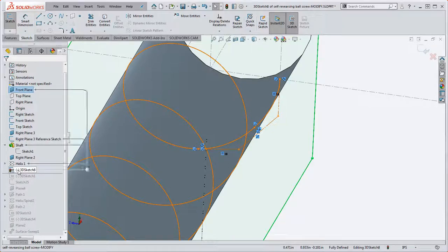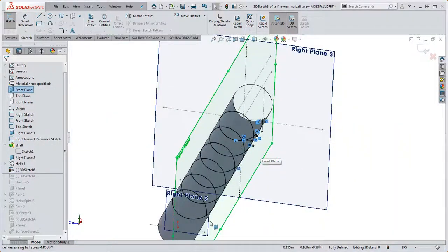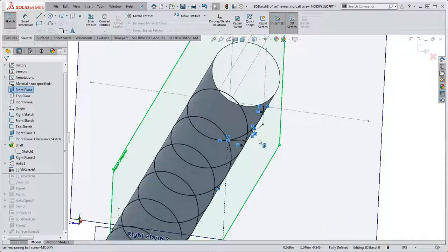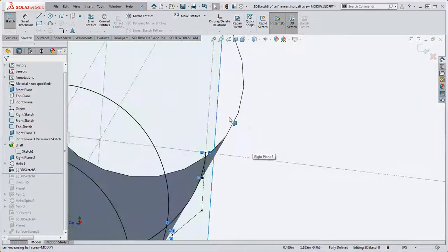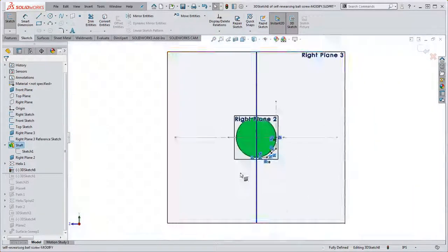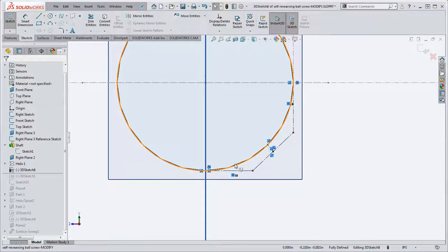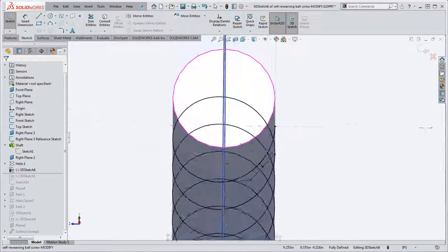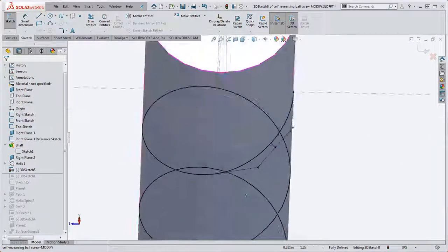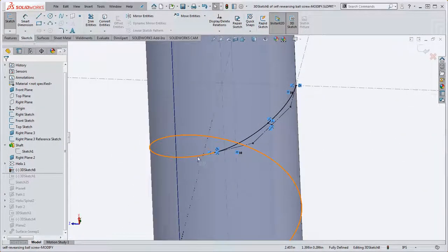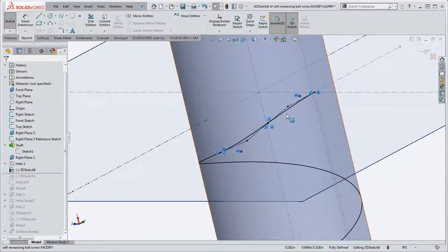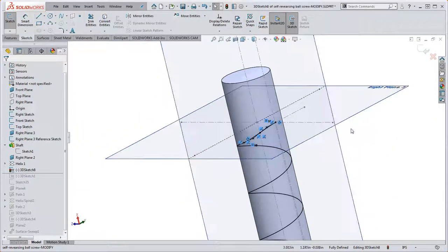You still might have a minus sign over here in your 3D sketch, just because the bottom point down here still needs to be defined. But if we take a look at this top surface and go normal to it, we can see that that curve is right on top of that cylinder. It's right on the surface of that cylinder. And if you look at the transition here, this transition's tangent, it transitions from the helix over here, elevates a little bit, comes over to the top, and eventually becomes tangent to that line. So now we have our path.